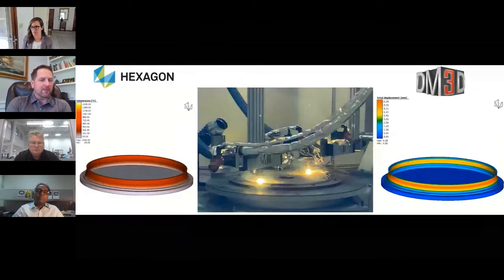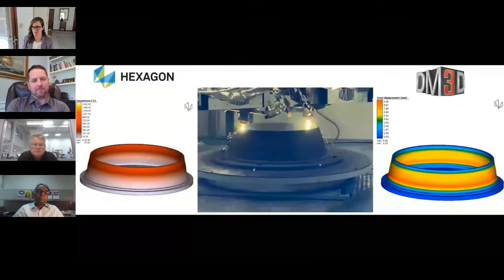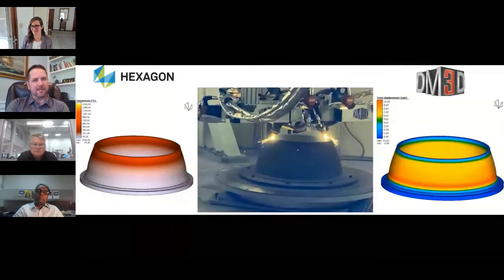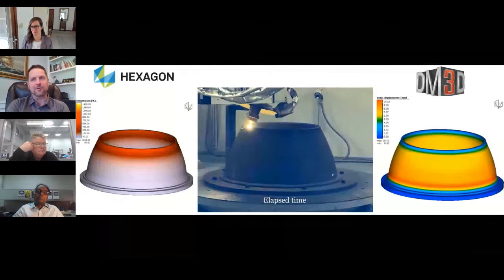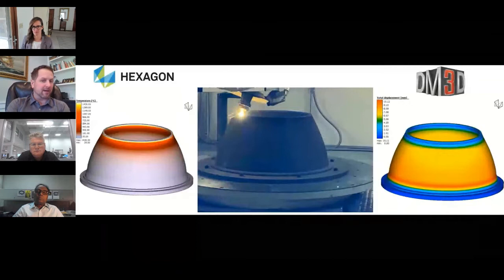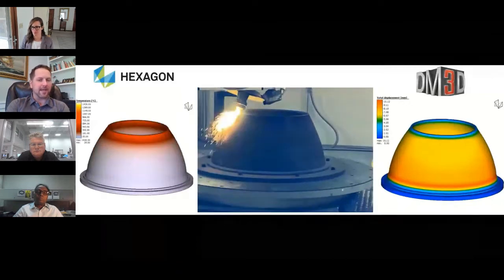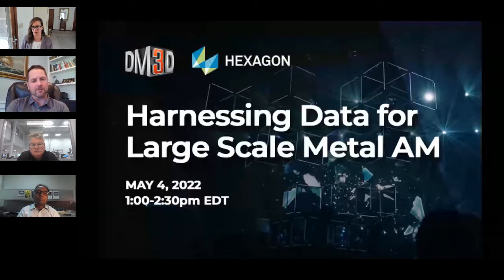So you start typically with a CAD, and then there's some pre-processing, slicing, and path planning that takes place. And that's kind of what you think you should get. The other piece that needs to be defined is the near net shape, which is not CAD. It's something that's slightly larger than CAD. Depending on the process type that you're using, that will define how much larger than the physical CAD net shape you're going to require. So that's an additional step that needs to be defined as well, and it is important to note.